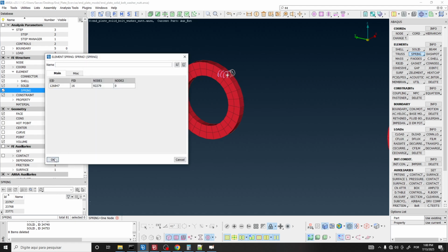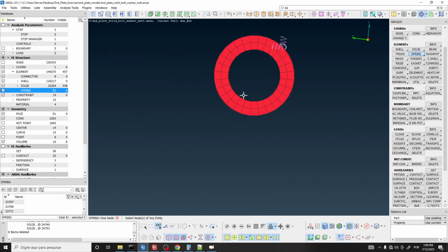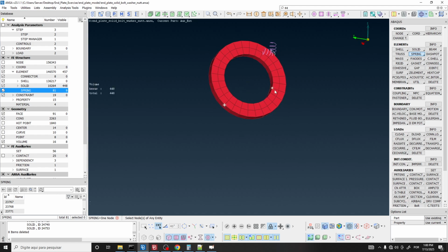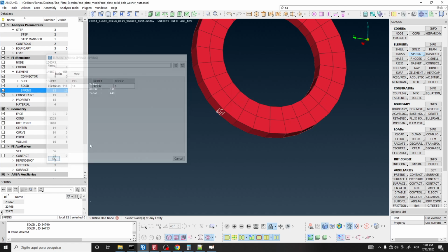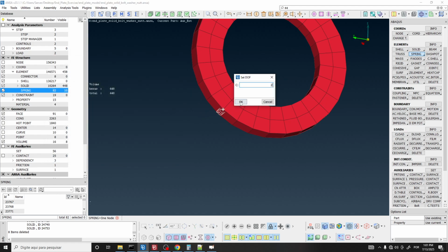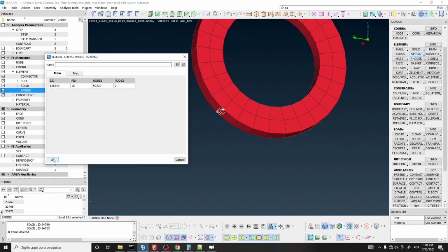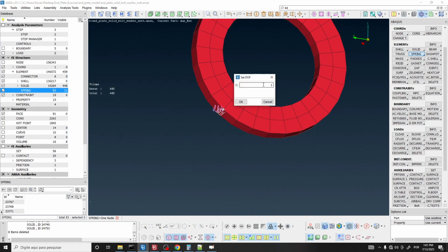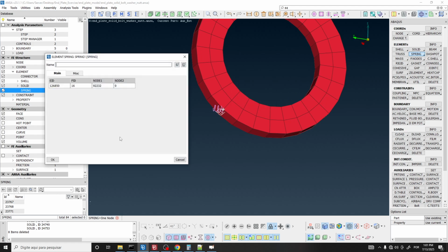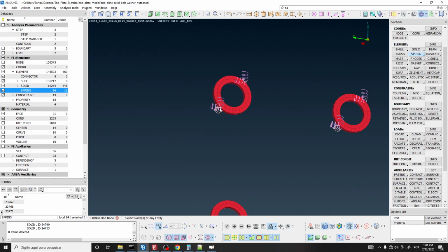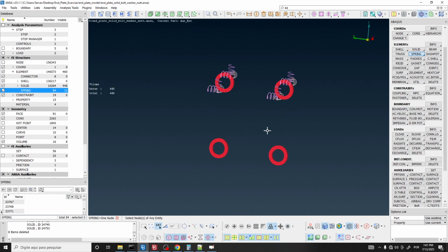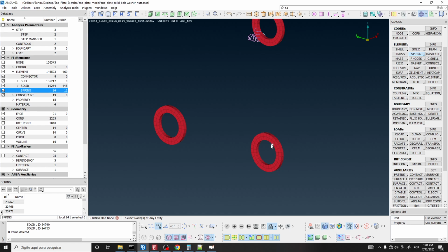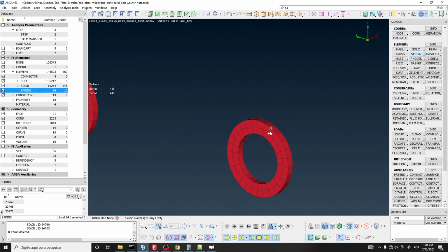Guys, one note here. These springs, we know that we are using them to stabilize the model, right? There are controls that perform this kind of stabilization automatically. But to be honest, I don't really like to use them because with these controls, we don't have complete control of what happens when we have them activated. So I prefer to do this in a more controlled manner.